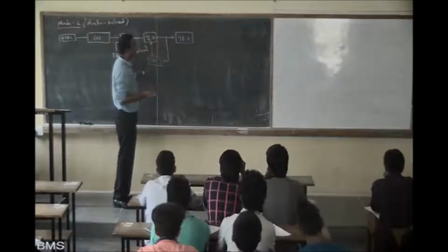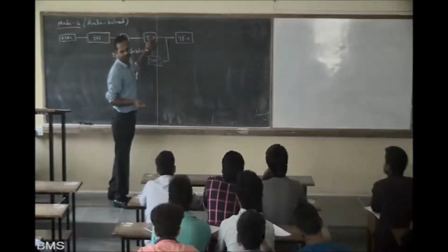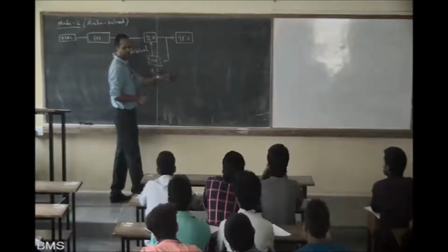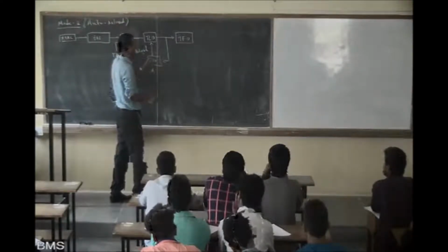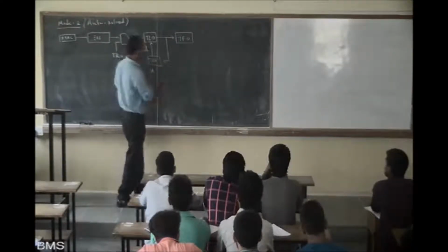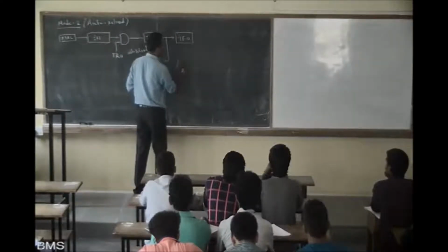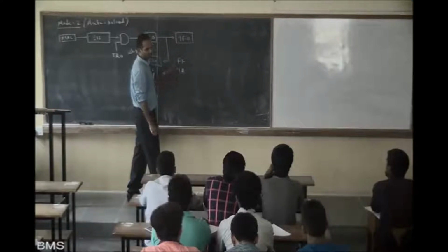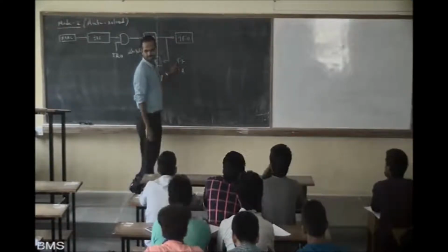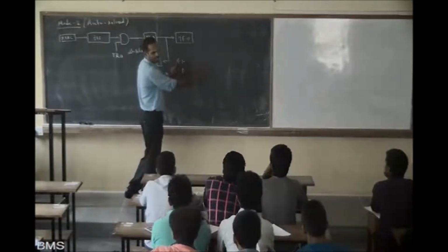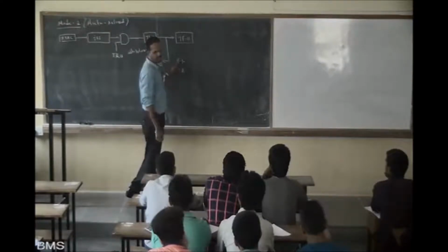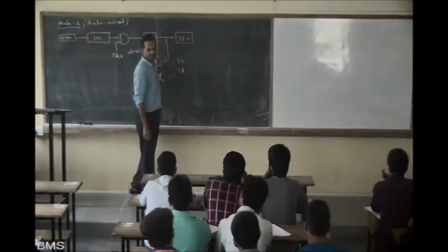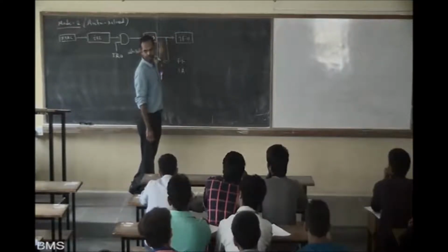Once it reaches 0, it will take the value from TH0, whatever value you have. For example, if you have 1A in TH0, then 1A will be loaded. You're understanding? So always the count is from 1A to FF, 1A to FF, 1A to FF till you stop it. How many cycles are there? 20 cycles. 20 times 1A to FF will be done using auto reload mode.